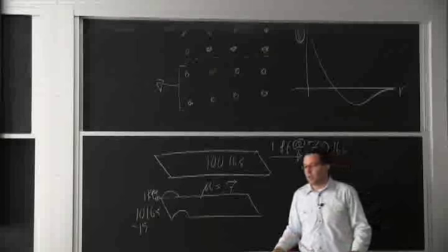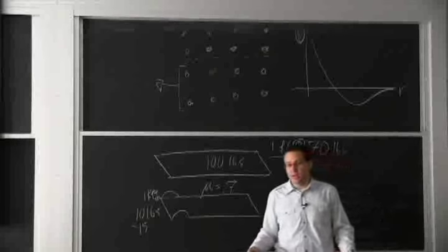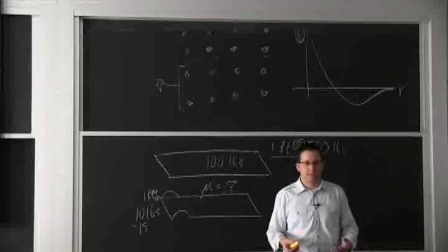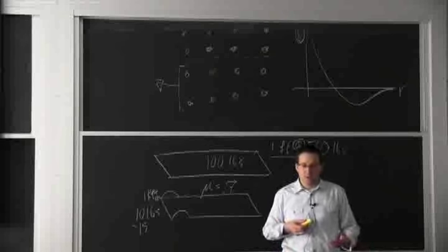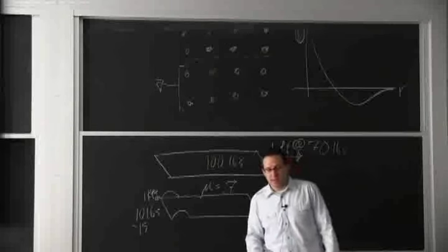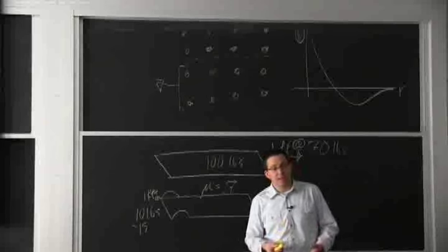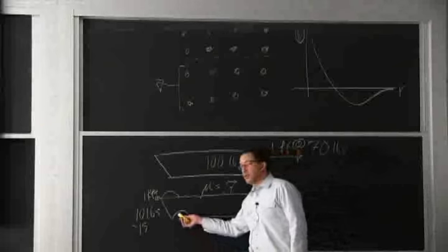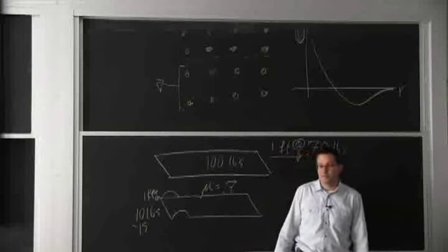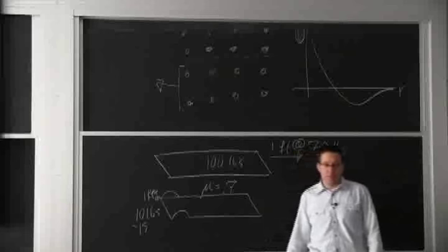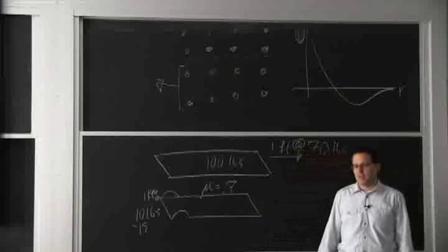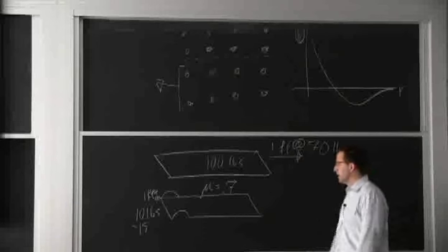And it also explains why steel at low temperature becomes brittle for impact loading. So if I really try to use a structural steel in Antarctica, I have to be very careful about what I'm doing, because some of these steels won't be able to make that fold at low temperature, and therefore they'll be brittle. They won't be able to deform plastically and accommodate to changes in the structure.